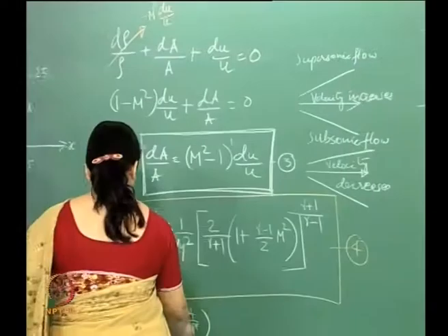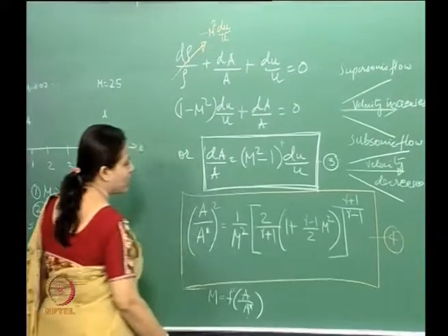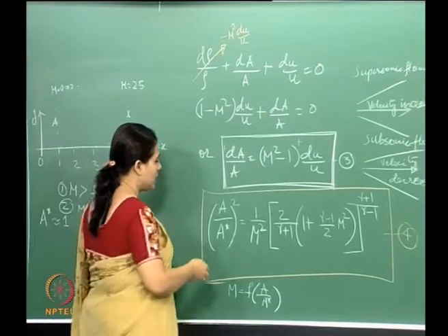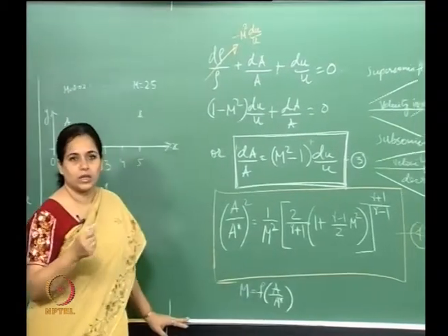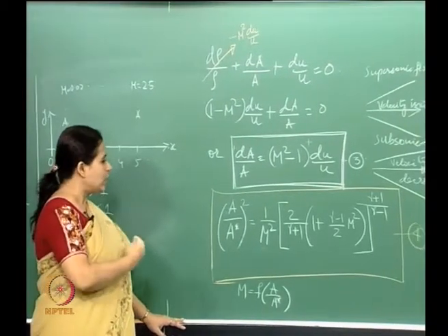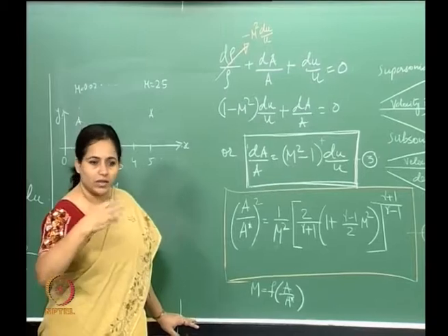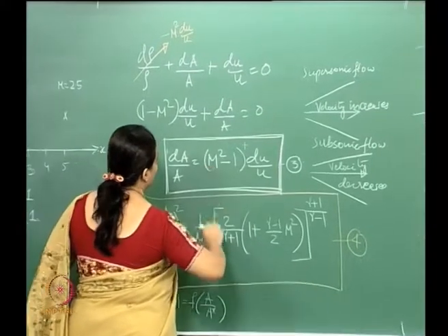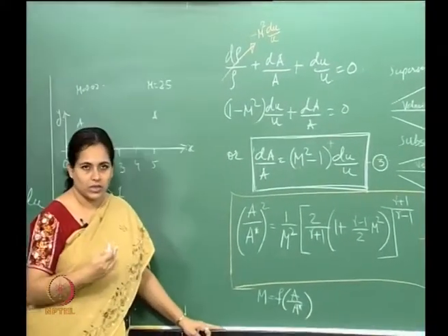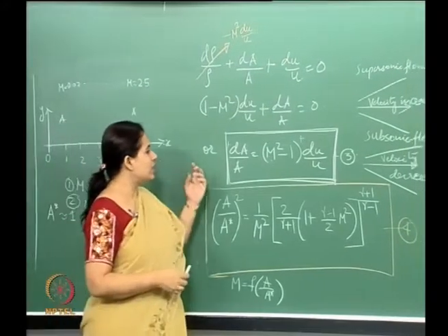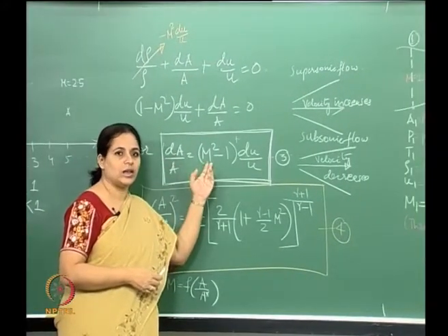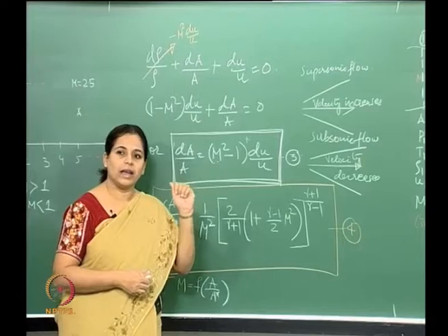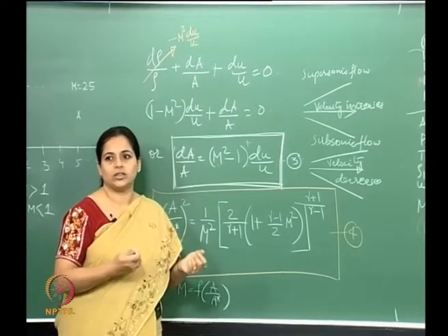If you come here, and you do this for a Mach 1, you will get a corresponding area. That is essentially the throat region, and I have just taken that, in this case, to be the least area. Based on that, we will get the areas of the rest of the duct, so to speak. Now, if you put M equal to 1 here, it does not make much sense, this relationship does not hold. What this equation means physically is that it is the least area in the distribution, right, the least area in the distribution.